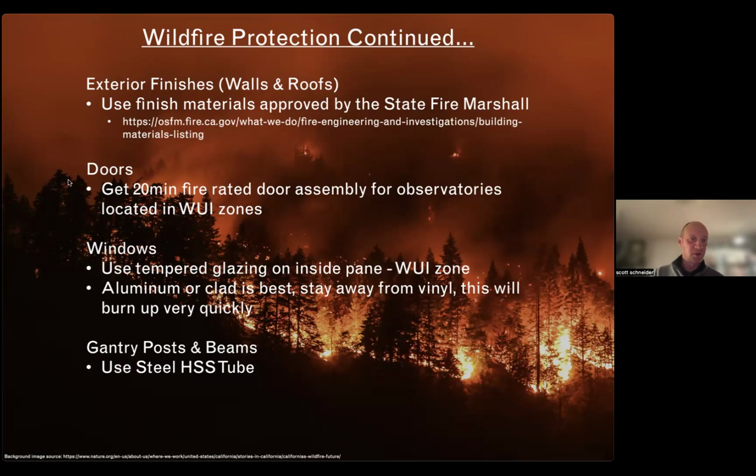For doors, get a fire rated door assembly, and it's actually the whole assembly that is rated, not just the door slab. Your typical door in a house is actually a 20-minute door, and you can get better, like 60-minute doors or 90-minute doors as well.